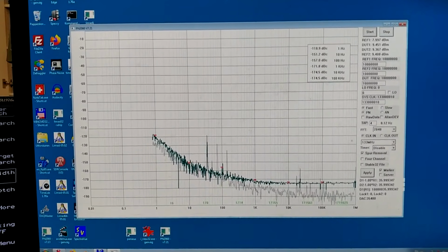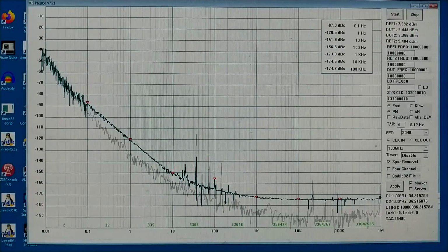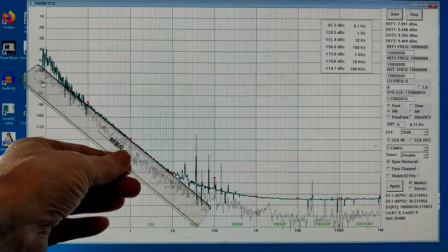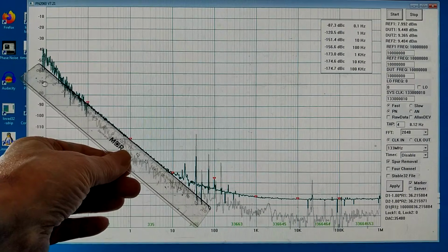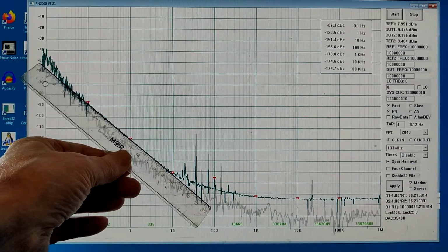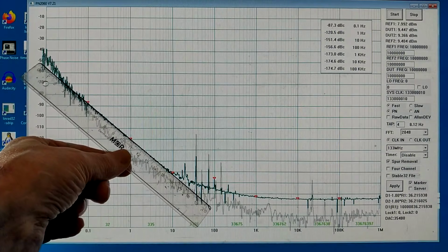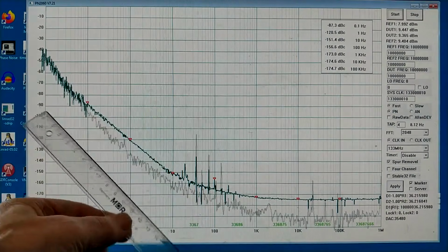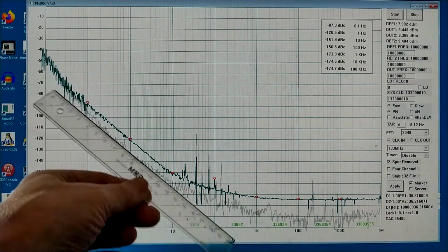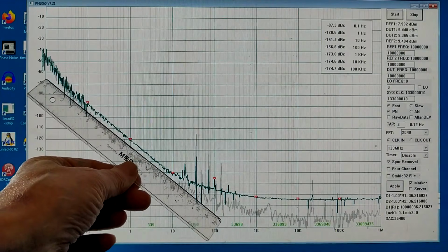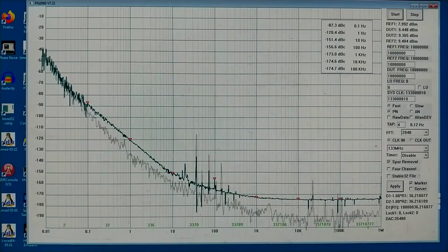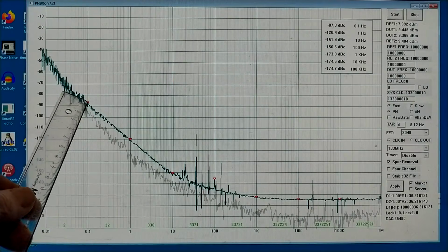Not particularly good, but not very bad as it was when I had it close to the series resonance frequency. I allowed the unit to run overnight. What I see is encouraging. The deviations from a straight line are very small. It probably continues well below 0.1 Hz offset from the carrier. There could be some steeper here because the straight line is pretty high. It should be something like this. But it's not bad compared to what I have had before, because I always had problems at 0.1 Hz.